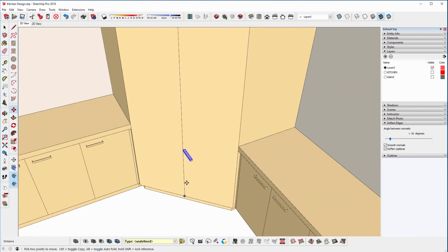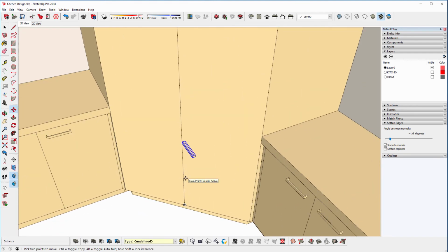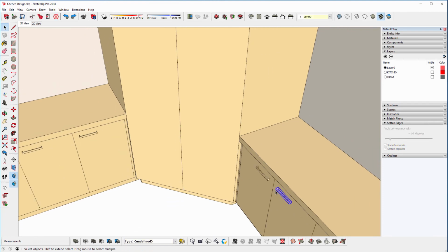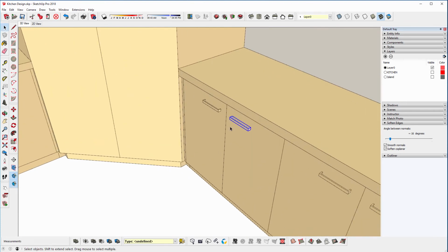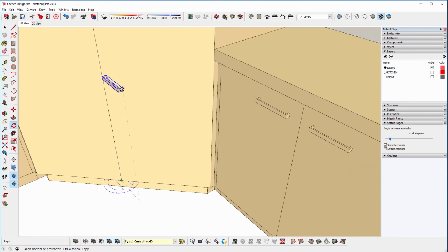And since it didn't quite go onto the surface, maybe we do one at a time. So if I was to do that one, copy, no, it's broken the surface, or stick to any surface. So if I copy that one to there, I could get the rotate tool, up arrow to lock it in the blue plane, touch this point here, click, and then I can line it up with this end point here, click.